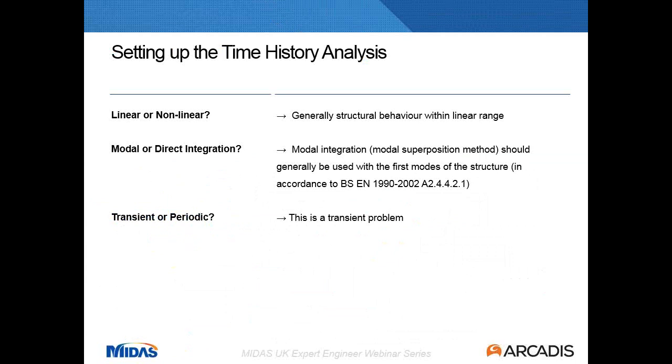So you should suspect that you will analyze the structure within the linear range. It's not explicitly said in the codes, but the assumption is that you will use a modal integration method, because that allows you to pick the modes that are relevant, as I just saw on this flowchart.